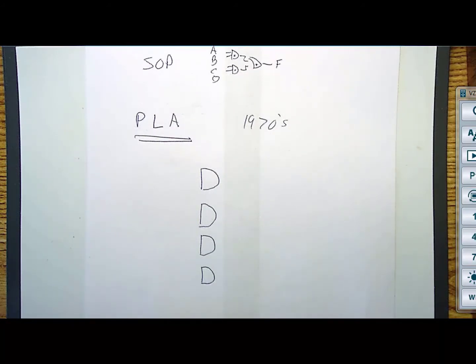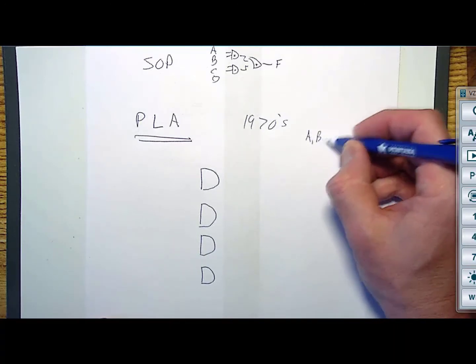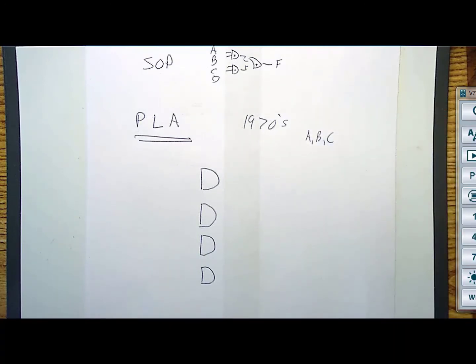Let's say you had into this system 3 inputs: A, B, and C. You know that in the worst case scenario, you would have a logic circuit with product terms which would include all of those inputs. Some of them might be inverted, some of them might not be included, but in the worst case, if you had 3 inputs, the largest number of inputs on an AND gate would be 3.